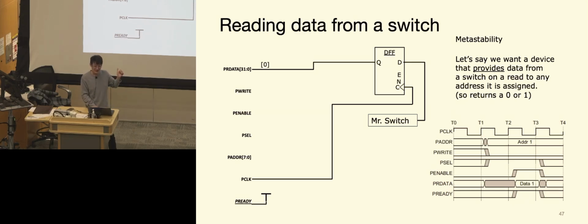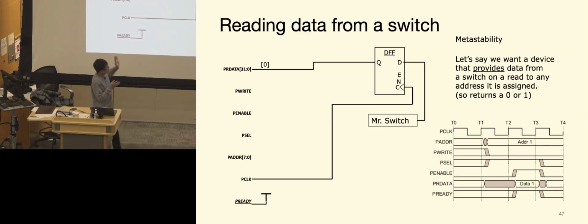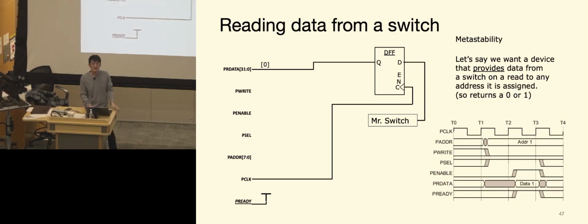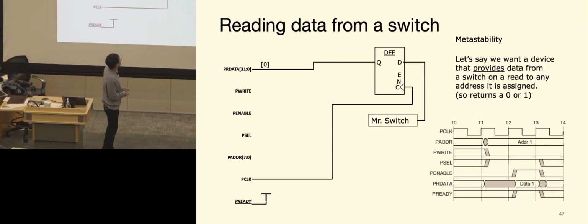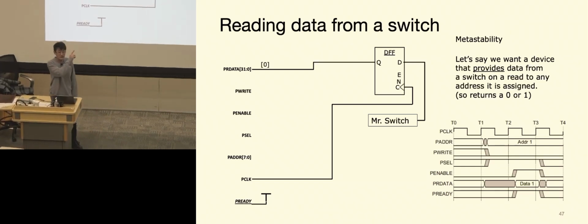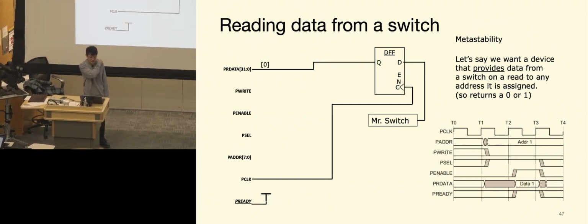This is very simple because we're reading from the switch. All the others are not necessarily needed here, but they do come in as the data inside of the data bus. But this is how you connect everything. With the enable and the clock? The clock only connects to the clock. It does not connect to the enable.